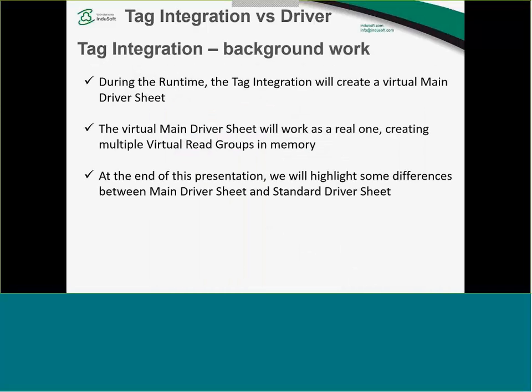During the runtime, we take all the integrated tags and we create a virtual main driver sheet. We're going to discuss the driver sheets in just a few minutes, because the main driver sheet is where you put all your addresses. As you start the runtime, the main driver sheet starts breaking into small virtual reading groups, depending on the protocol limitations, the block size on each protocol, and the protocol rules. Okay?